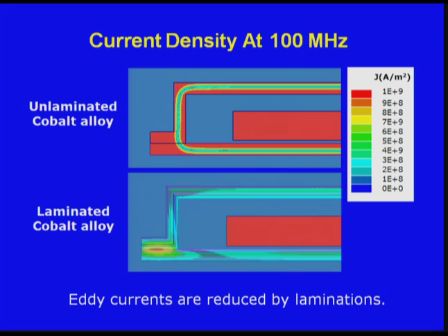And what you see is that there's a lot of eddy currents that flow on the bottom surface of the magnetic material. They get to the end of the inductor, they turn around and wrap and come back along the top of the magnetic material. So that's what you would normally see in a laminated transformer or something. So the thinner you make your laminations, the better, because now the resistance that current has to go through is higher, because it's basically thinner magnetic materials. That's how lamination works. Well, with these structures, we have a disadvantage.